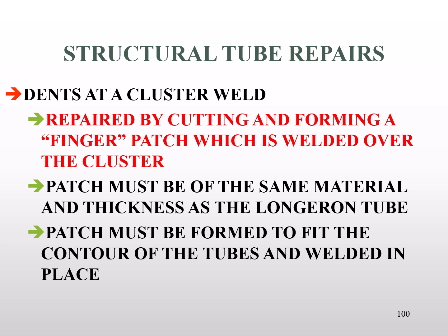On this slide, because we've already talked about how you could form a finger patch or steel patch for a dent at a cluster joint, when you select materials to make the repair, the importance on this slide is it must be of the same material, the same thickness. It must fit and conform.